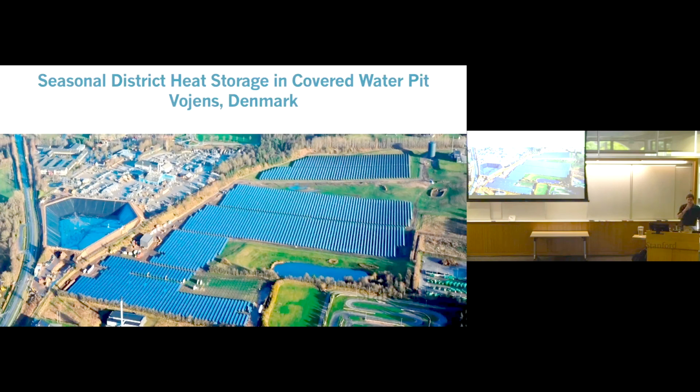Question. Is there a way to do this but for cooling? In fact, you could. Well, the one I'm not going to show is the aquifer storage, which they have in several places in Europe, where you have an underground aquifer under some bedrock, and then there's a water level. What you do is you actually have two sides. On one side it's for cooling, one side's for heating, and you have pipes going up. And so let's say in the winter, you want heat, so you transfer hot water from the hot water side, and then you heat the buildings, and then you send the cold water that results down to the cold water side. And then in the opposite season, the summer, you take the cold water from the cold water side and you move it to the hot water side.